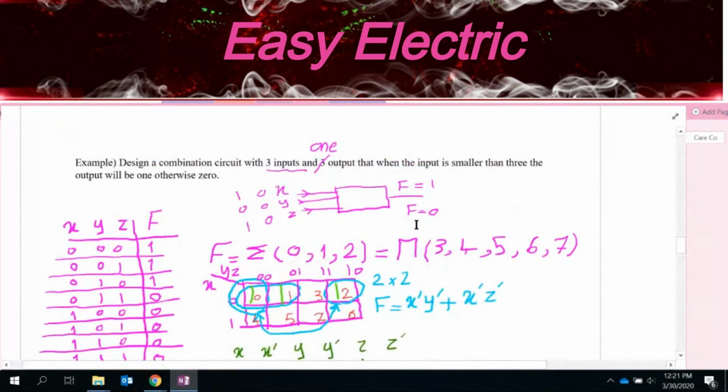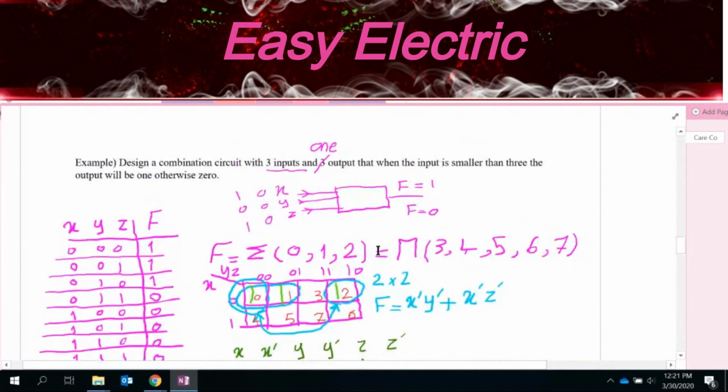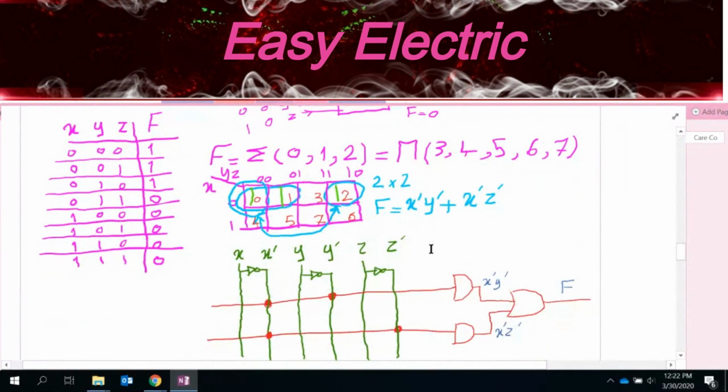So right now, if you need any circuits, this is the knowledge that you need to get. Whatever we learned so far is just for this concept, right? We want to be able to design any combinational circuit that we need. As engineers, you should be able to do that, and based on the knowledge that you got, we are able to design that circuit in the simplest form possible, because we use the K-map, which ends up with the simplest form.